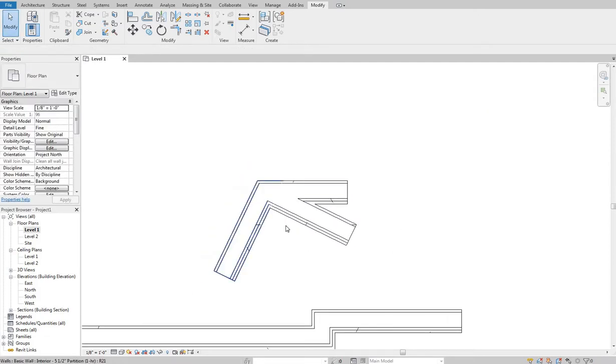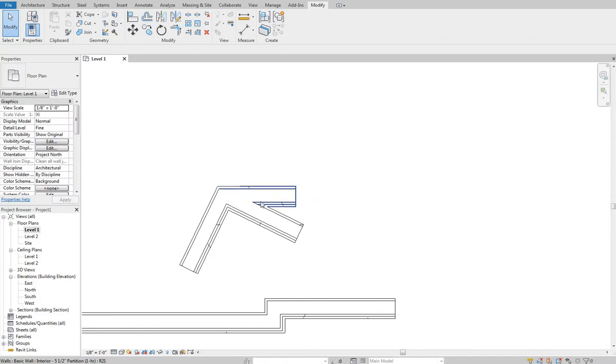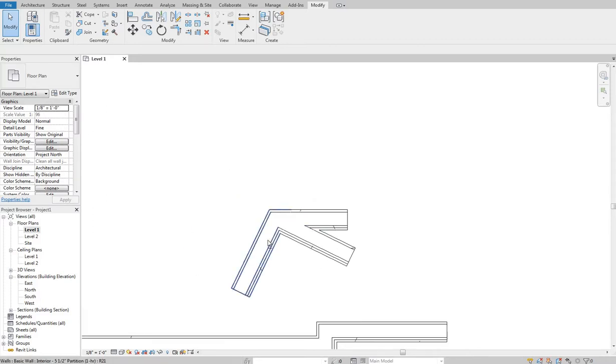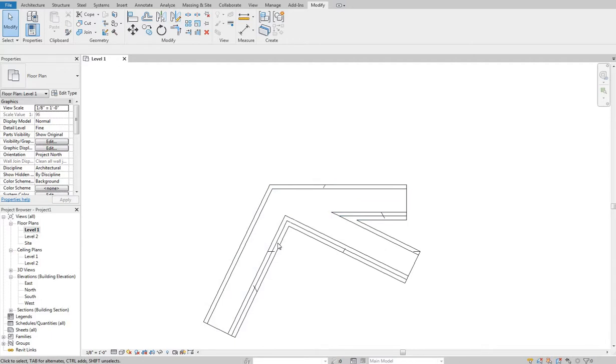This is also important when you have windows very close to corners, because occasionally a layer will stick into the window and you might need to come up to the wall joints and just throw that on miter or something like that to get rid of the structural layer sticking into your window. Because maybe you have a window in this wall right here, but if this is coming in and this structural layer is sticking into this structural layer about here and your window is right here, you're going to see that little piece coming through because the window is cutting this wall, not that wall.